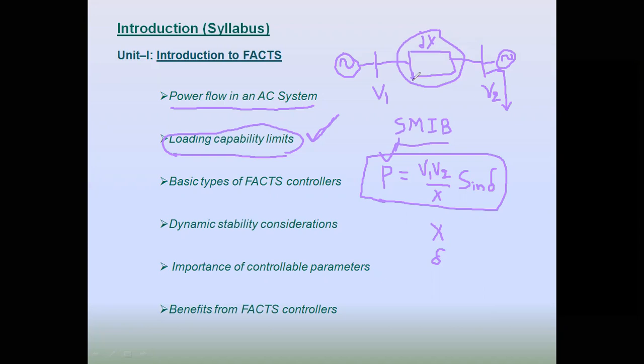So in the case of transient stability, we are analyzing the system behavior even during the faulty conditions. One example that we are considering for analyzing the transient stability is the swing equation, using the equilibrium criteria. From the swing equation, a number of methods are there to solve it. We solve that by using the equal area criteria. We take power along the y-axis, mechanical power and electrical power, against delta, and the fault condition. We are assuming that mechanical or turbine power is constant, and electrical power will vary with delta as given by the above equation.